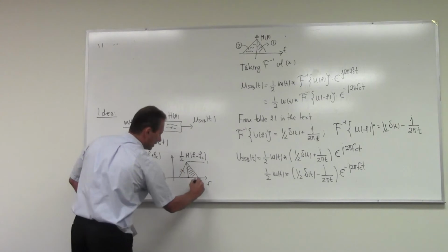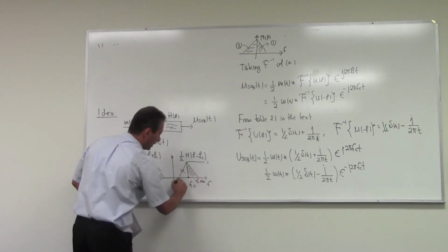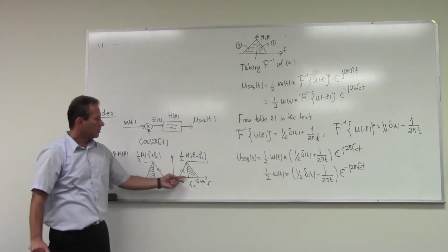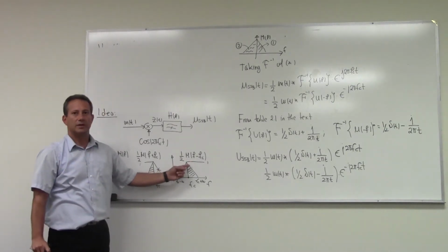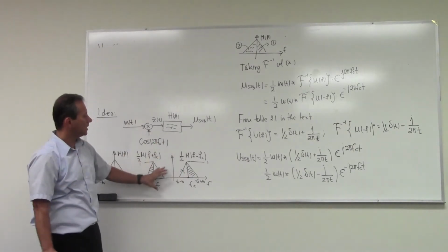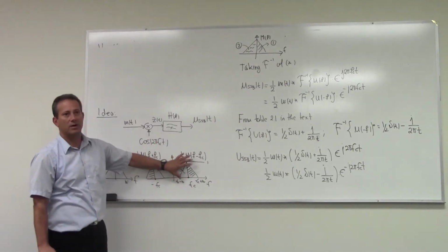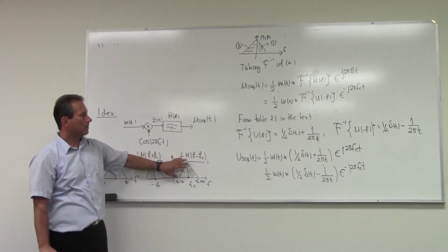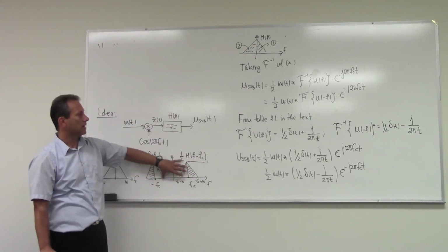This is fc plus W here, and fc minus W, and the same thing on the other side. So getting a step function filter at a very high frequency is close to impossible. So even though this illustrates the idea, this is not a practical way how we can do this. So we need to have a better way of accomplishing the same task.